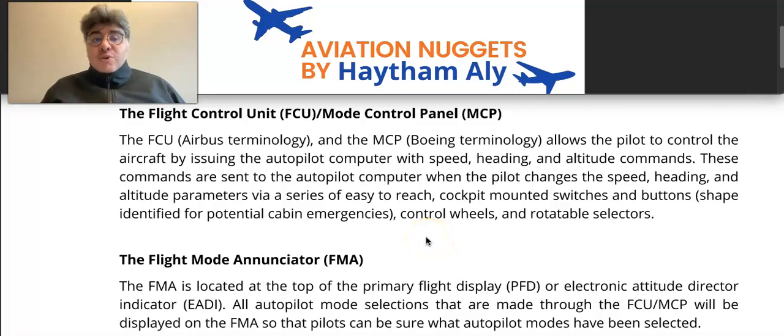What other component is there for the autopilot? It is the autopilot computer and the actuator, which may be an electro-hydraulic actuator, or maybe an electro-pneumatic actuator. The actuator, or servo control, is located on the flight control system. Because when the autopilot is engaged, the autopilot sends the control signal to the flight control system. Through what? Through the actuator.